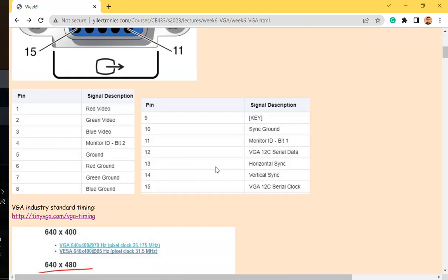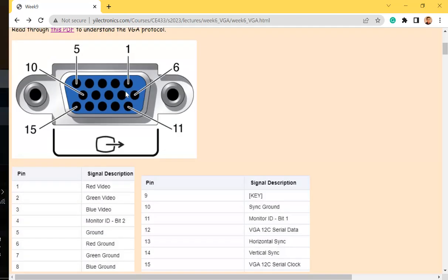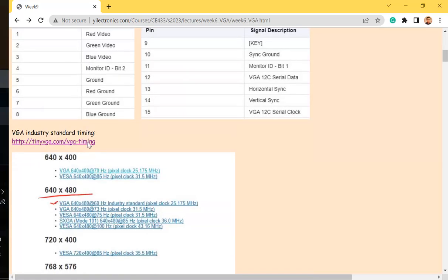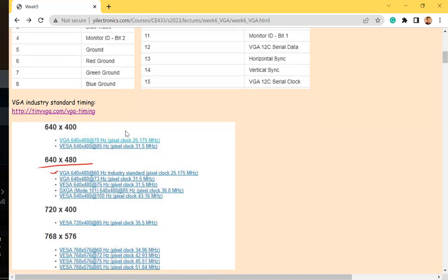And these are the pin outs. So that's the pin out of the VGA port. And in the constraint file, when you are working on it, don't forget to uncomment that VGA portion of the constraint file, otherwise you couldn't do it. So these are just certain pins on the FPGA.